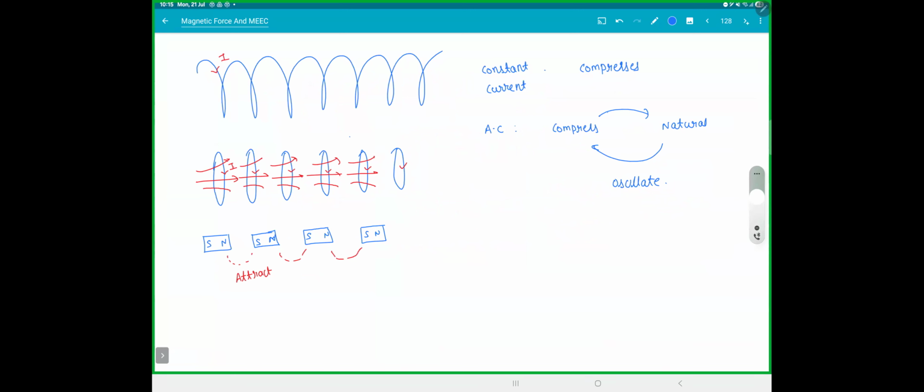Because when you go to a shop and ask for a copper wire, most of them will give you an insulated copper wire. So the copper wire will have a plastic coating. First, I didn't realize that. If you have a plastic coating, what will happen? Even if the magnet touches, your current won't flow, right? So you need to get a wire without any insulation on the top. And second, once you get the wire, it should be sturdy enough to make into a coil. And the coils should not touch each other. If they touch, it will get shorted.